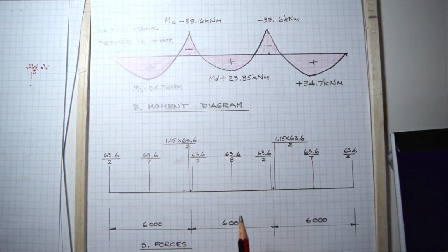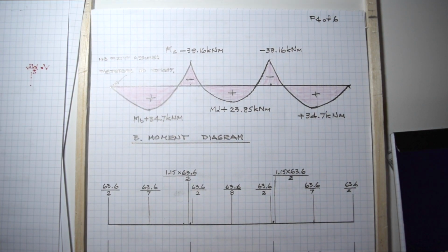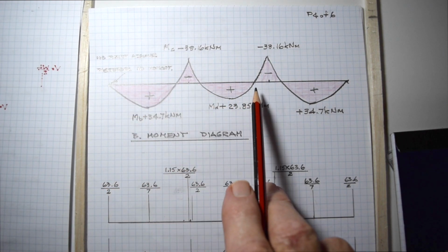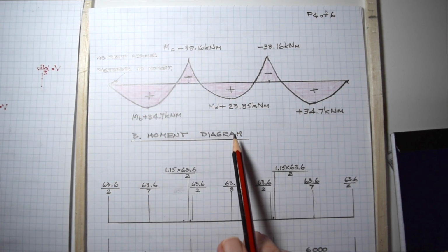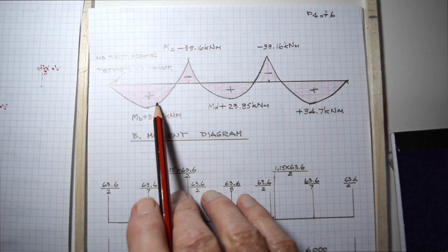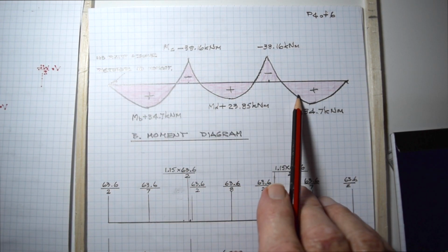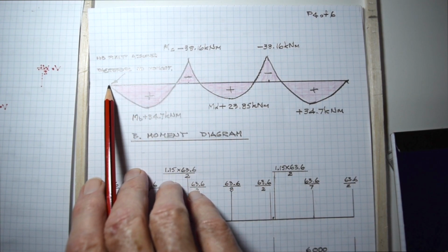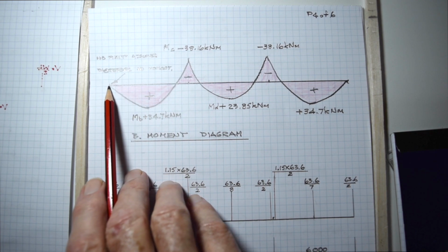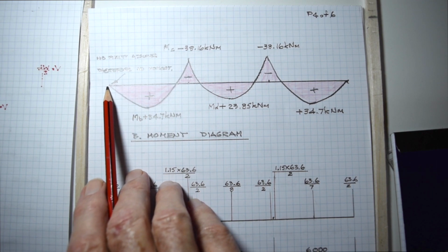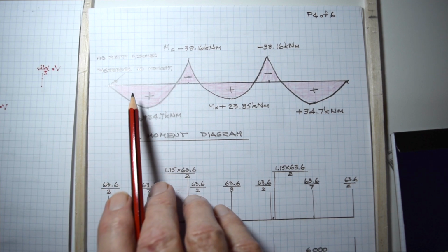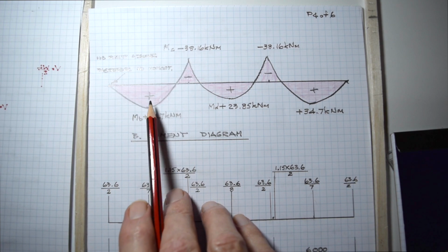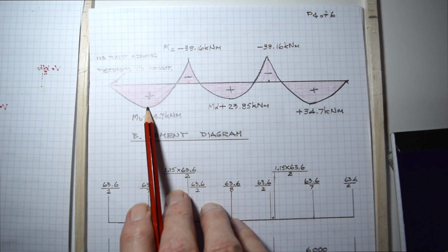And to come back to the diagram then, if you sketch this out, it might not look as nice and tidy as this if you took into account the fact that there's a moment envelope, but I've encapsulated all this in a 3-span beam moment diagram. With your positive moments, I've assumed that there's no fixity there, there's no connection between the slab and a beam. It's simply supported on a brick wall, I've assumed. So there's no bending moment there. Your maximum moment from the computations we've been doing is 34.7 kilonewton meters there.